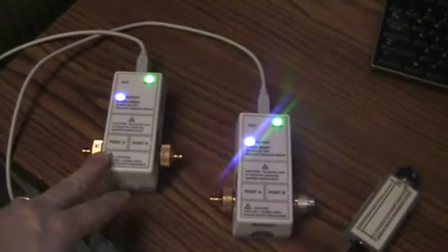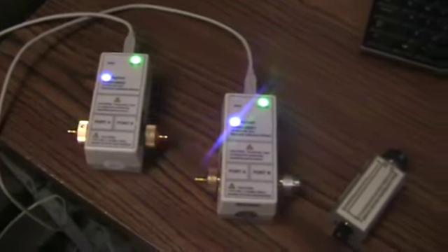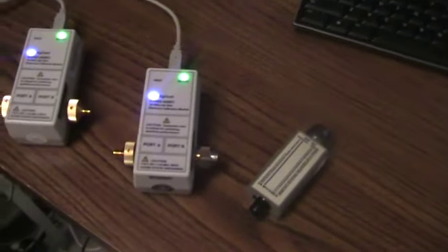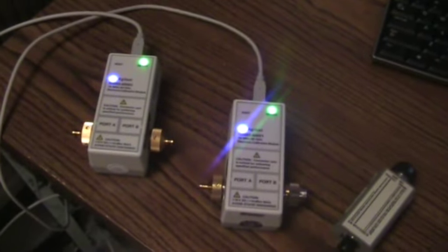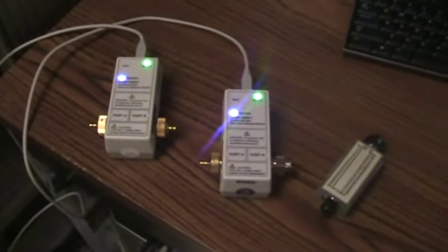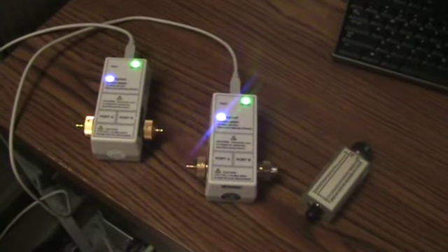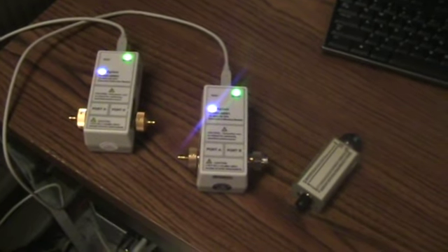This one right here is a 50 gigahertz with 2.4 millimeter female connectors on both sides. And this one over here has the male connector, which is used during the calibration. If you don't have that extra standard, you can either use mechanical standards or do an adapter characterization onto one of the ports on the other eCal. So I'm going to get started with the procedure by showing the PNA-X screen and some of the steps that we go through in order to perform the calibration.